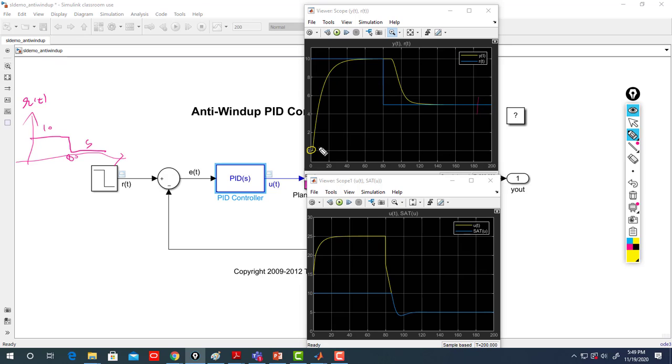That's why when you have the real robot, the real physical system, sometimes you need to slightly tune more to overcome everything in the physical system which you didn't cover in the simulation. Anyway, what's happening here? When I first commanded 10, we have error, but the controller gives a very high signal to react from 0 to go to 10, and especially we have time delay. That's what makes it take some time.